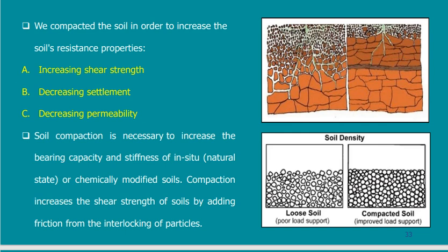And so on. If I add stress on top of this soil, particles will come nearer to each other, and once they come nearer, soil particles start to touch each other. In this case, I am really increasing the shear strength of the soil. Why? Because air and water have a shear strength of 0.